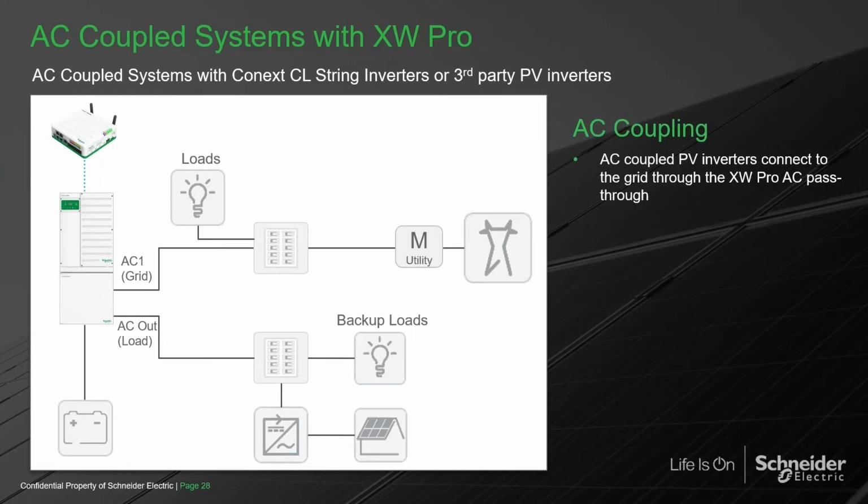The grid tie inverter really does all of the work in normal conditions. And what do I mean by normal conditions? I mean that the grid is present and is qualified and available. So the grid tie inverter does its job, which is simply to inject current, synchronized to the waveform of the grid, and is injecting as much power as it has. So the power generated by the array is first consumed here.